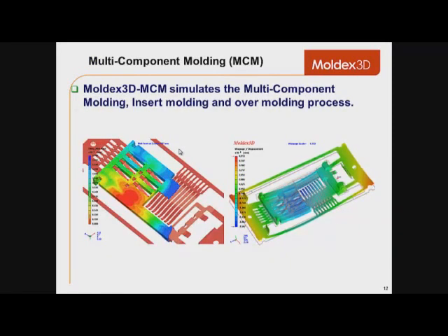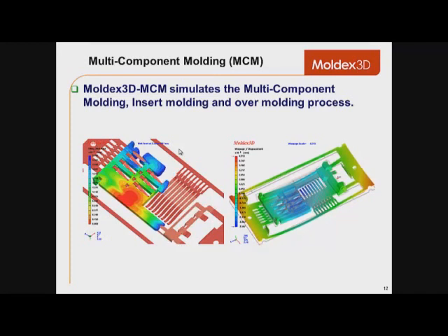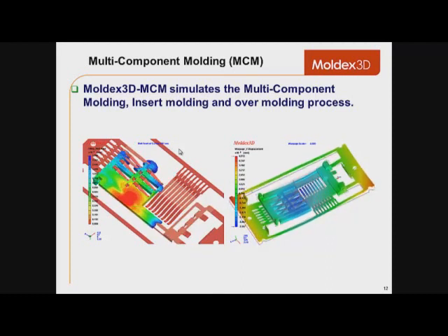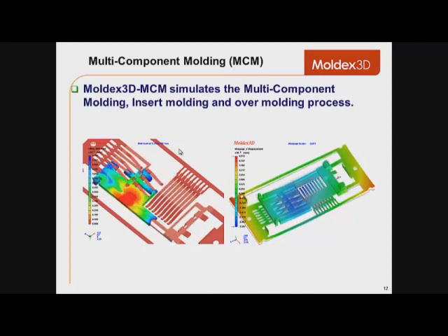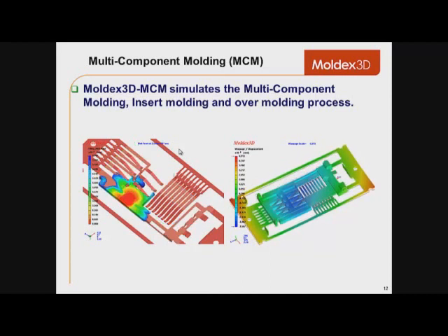With this tool on this slide, you will be able to simulate part inserts, mold inserts, and two-shot molding, also known as overmolding. Here, we see both the flow simulation of the plastic part over a part insert, as well as the warpage that will result from this flow.